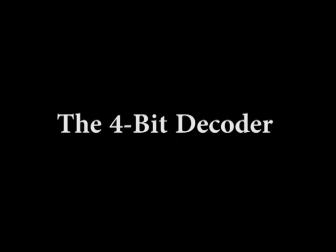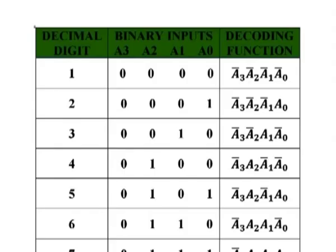The 4-bit decoder. In order to decode all possible combinations of 4 bits, 16 decoding gates are required. This type of decoder is commonly called a 4-line to 16-line decoder because there are 4 inputs and 16 outputs, or it could be called a 1 of 16 decoder because for any given code on the input, one of the 16 outputs is activated. A list of the 16 binary codes and their corresponding decoding functions are given in the table.